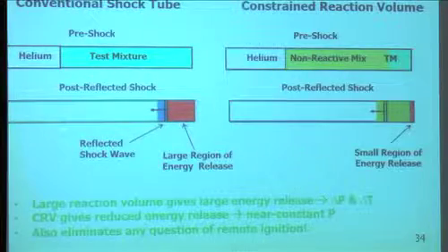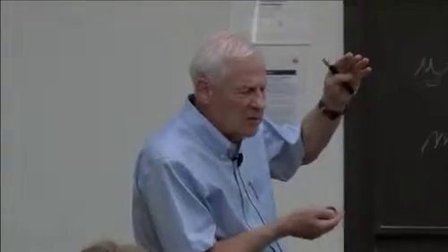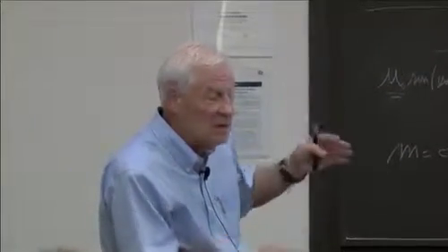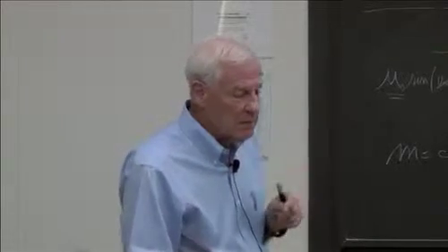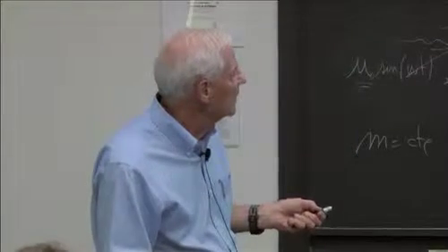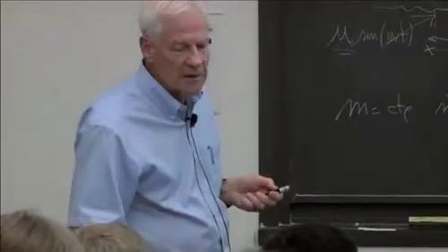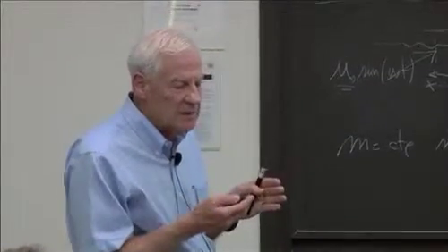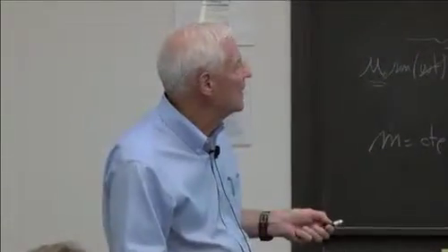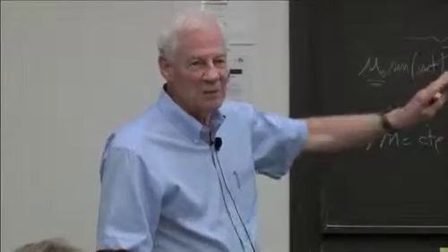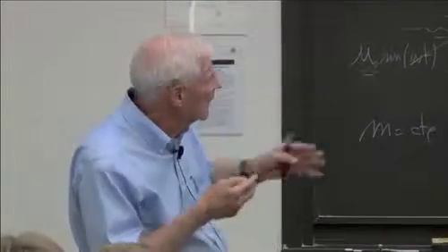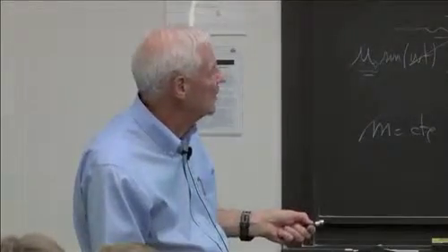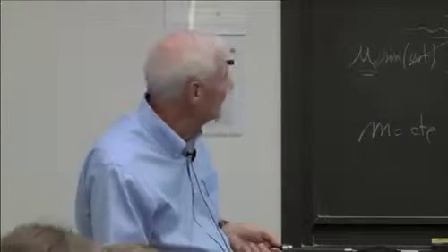So for a long time, people said, why are we getting these strange laboratory to laboratory differences in ignition delay time at low temperatures? The ones that I showed you are explained by dP/dt. Well, I said it's mostly dP/dt. But still, we can find in our laboratory that we still sometimes get ignition out here in certain temperatures. I call that the remote ignition problem. This method avoids remote ignition. There's nothing out there to burn. So all questions about, are you sure you're not bothered by surface reactions, all those problems go away with this idea. Now we buy a new problem, but this has got a lot of potential.